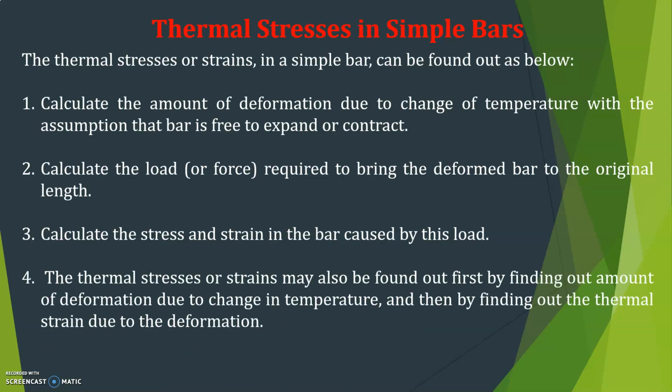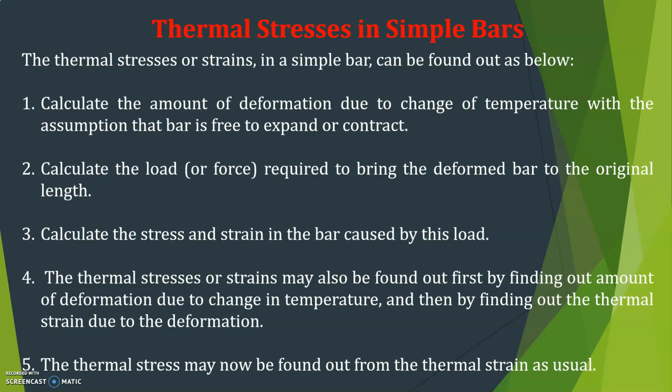Then the thermal stresses or strains may also be found out by first finding the amount of deformation due to change in the temperature, and then finding the thermal strain due to the deformation. Any method you can use. The last one is that the thermal stresses may now be found out from the thermal strain as usual.